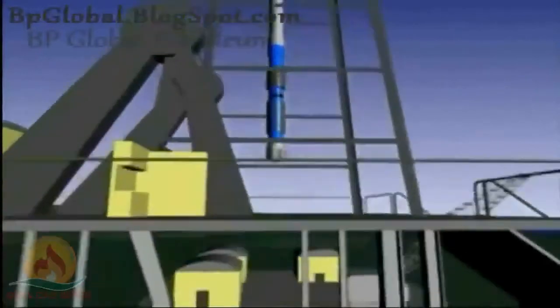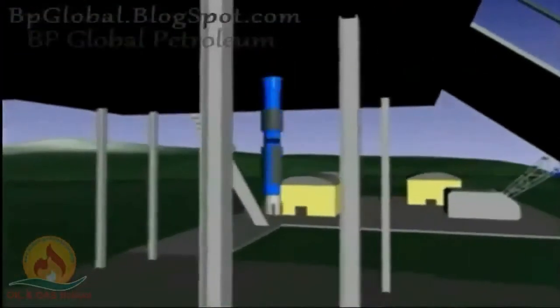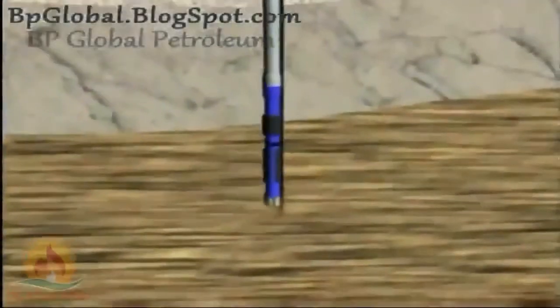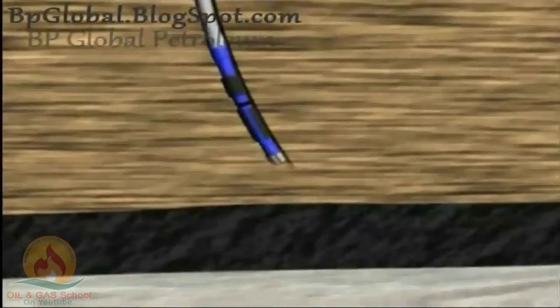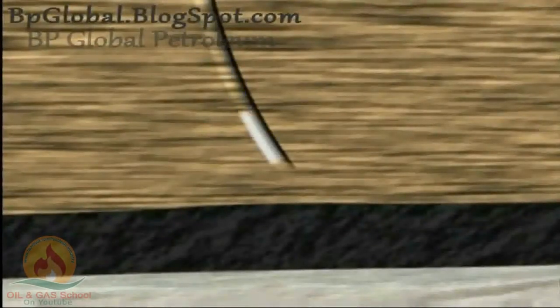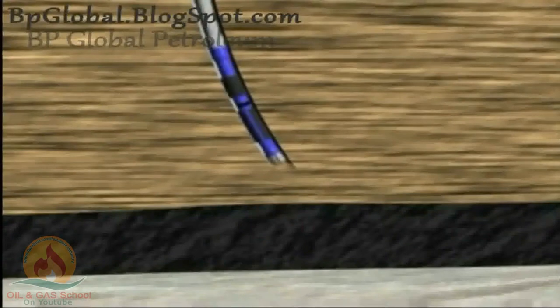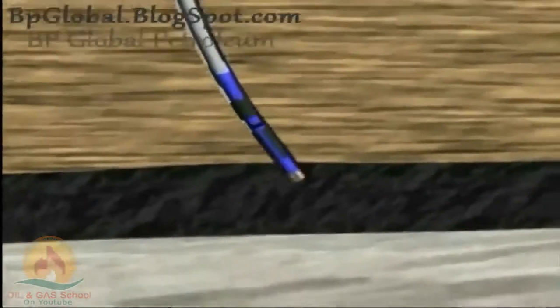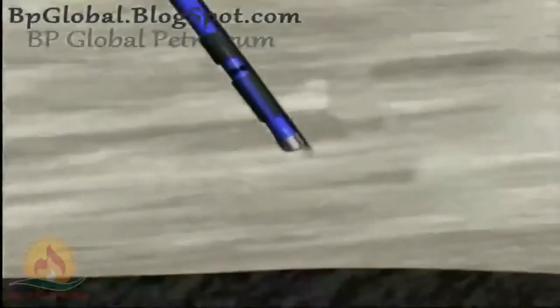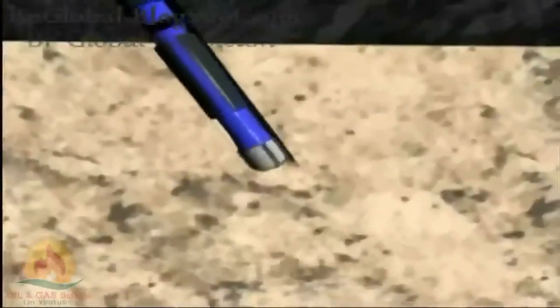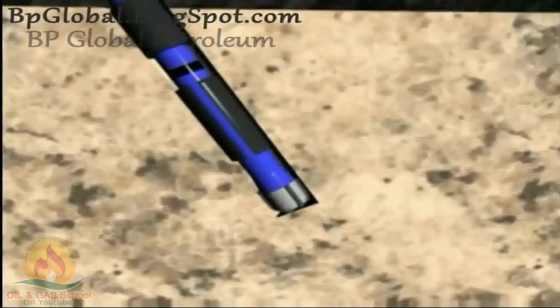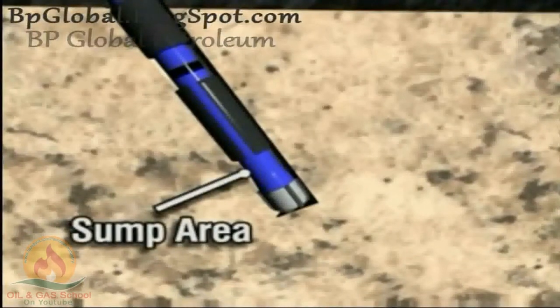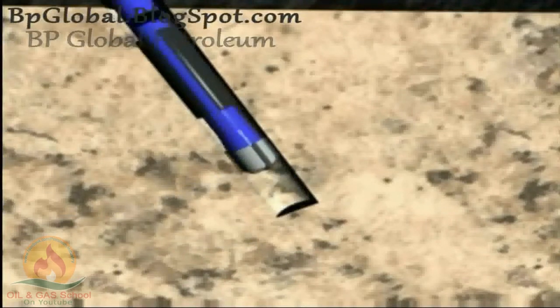We begin the process by drilling a deviated wellbore to a joint just above the productive coal seams. Casing is set and cemented into place. We then drill a pilot well through the productive coal seam, and the wellbore is extended for 100 feet below the deepest coal seams to be accessed. This extra 100 feet serves as a sump area for collection and disposal of produced formation water.